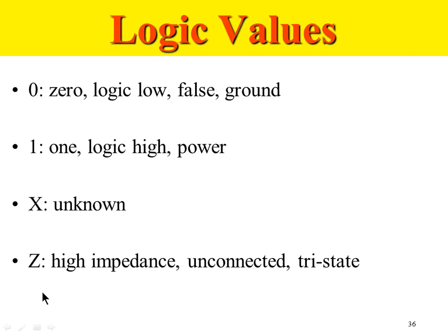Your signal can be logic 0 or logic 1, or in certain cases, high impedance, Z value. Typically, the Z value is allowed when you're dealing with a bidirectional bus or a bidirectional signal. The direction that is currently used could be logic 0 or 1, but the other direction which is not used will be tri-stated, or in high impedance state, to ensure that the data is not flowing out the other direction by mistake. Typically, high impedance values or tri-state values are used for bidirectional ports or bidirectional pins.